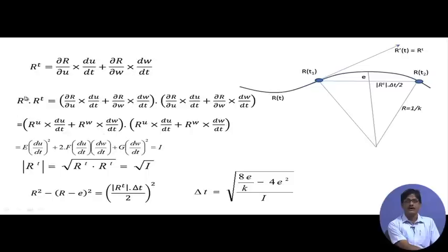So, what do we have here? R t, that means the tangent along the cutter path can be expressed in a chain form. This is the complete differential. So, this is basically dr dt expressed in chain form, because r is basically a function of u and w, and r t dot r t, if we take the dot product of the tangent to the cutter path with itself, we have these two dot producted, and ultimately it gives rise to this expression. How do we have this?